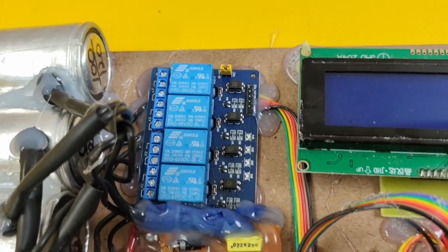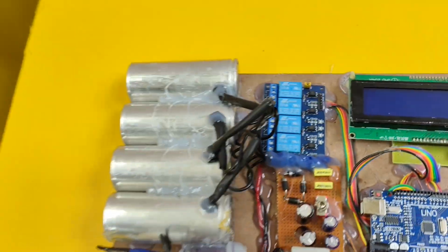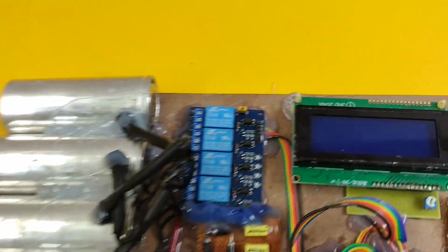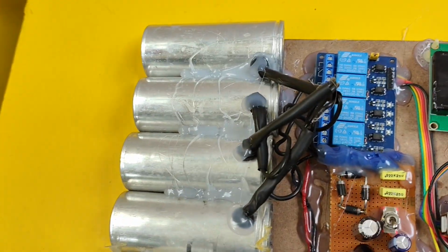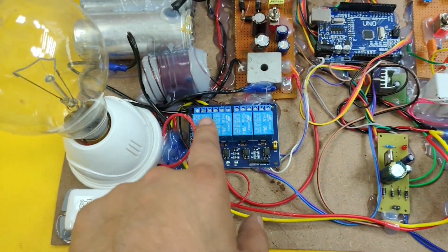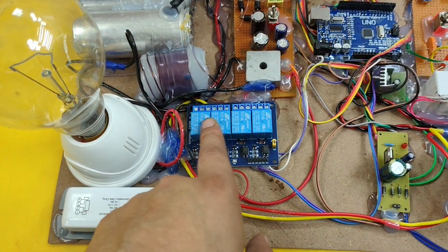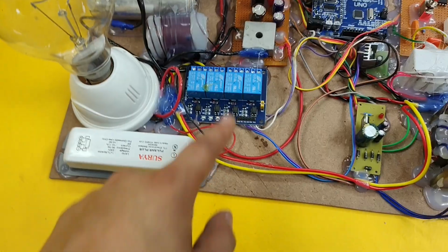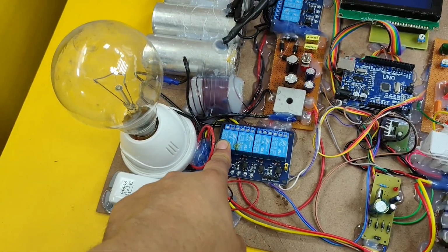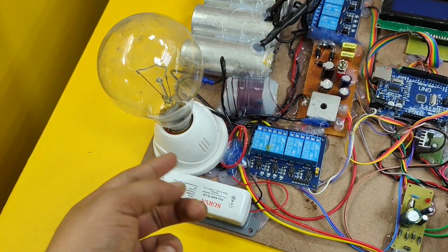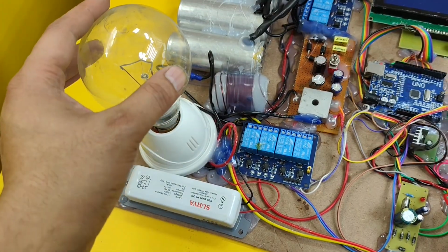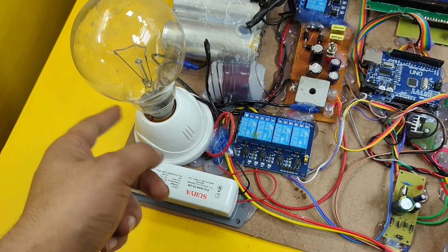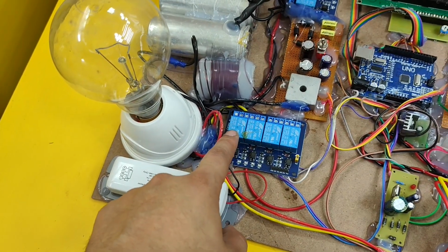So these 4 relays are basically activating these high industrial capacitor banks. These are the high power capacitor banks. So 4 relays are connected for these capacitor banks, and these 3 relays, 1 relay is spare, and these 3 relays, 1 2 3, are for specific purposes. Let me tell you, the first relay is used to select the resistive or inductive load, or you can say capacitive and inductive load, because it has induction as well. So this is your capacitive load, and this is the inductive load. It will be selected with the help of this first relay.